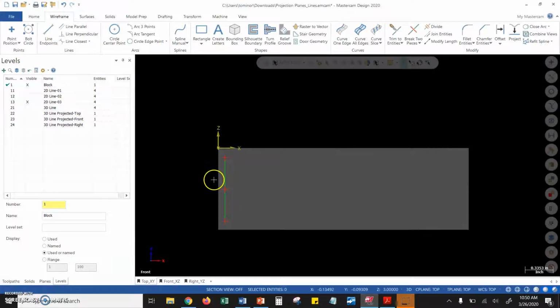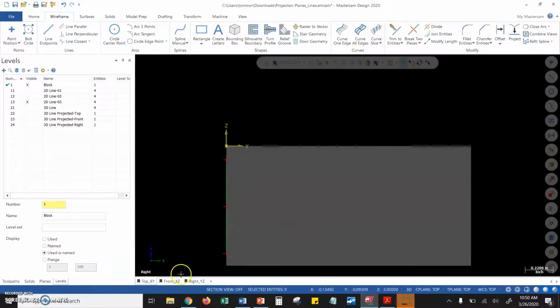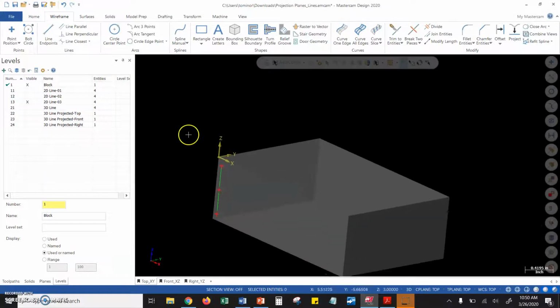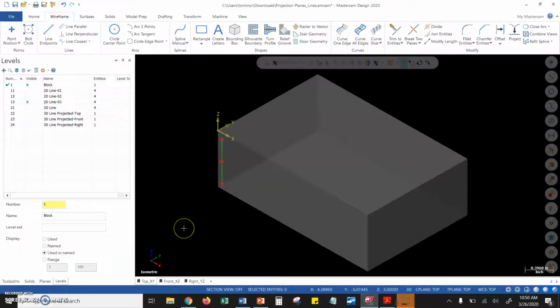We look from the front view. Now we can see that that is a vertical line. We can see its length. And then looking from the right side view, we can see a vertical line, but probably not as much usable information as we could see from the front. So I guess the key takeaway here is, depending on what you're trying to measure on a CMM, it's very important to tell the CMM how to look at it.